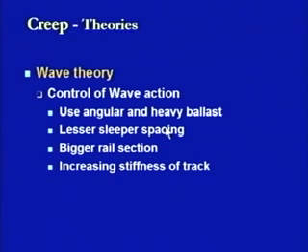Angular is required because as soon as the ballast is angular or the stones are angular, they will start fitting in with each other, and if they are fitting in with each other, then they will transfer the load through their point of contact from one stone aggregate to the other stone aggregate. And if this is happening, then the load will get transferred to a much wider area. So, this is why the angular stone or ballast is required.